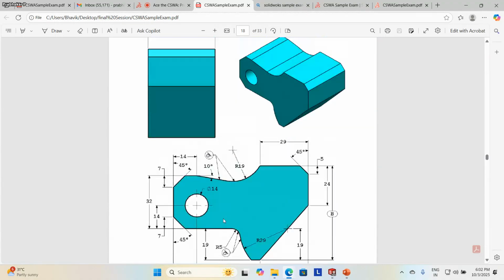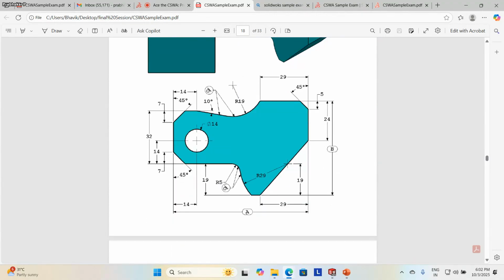part modeling task. Okay, so what you need to consider is, one, time management is key. Once you see the model, how you are going to build it, the model may require extrude, or revolve, or sweep. So what command is required, you need to plan. At the same time, which plane you are going to build on, and how many planes you are going to use. That is important.